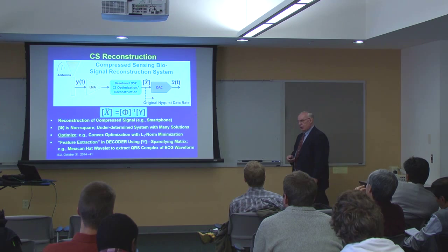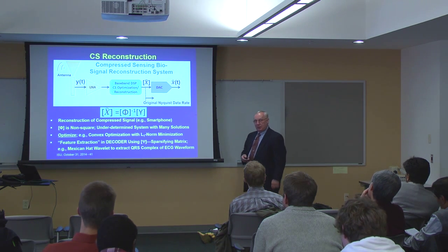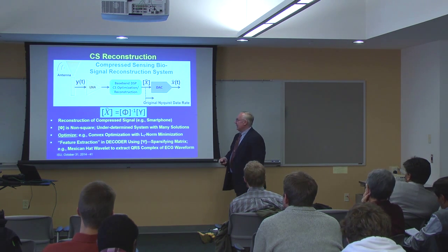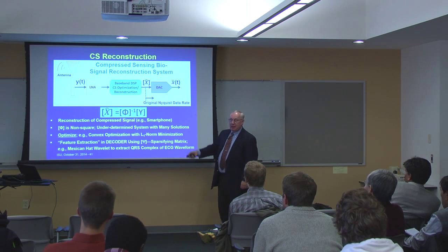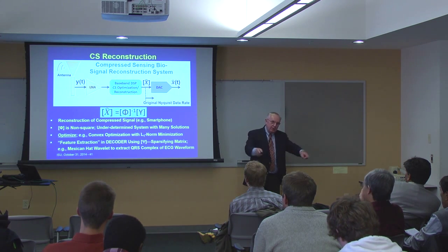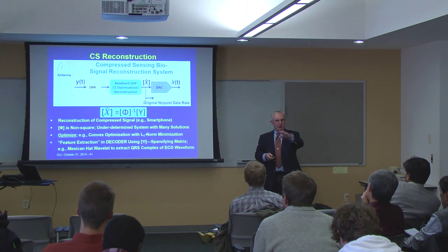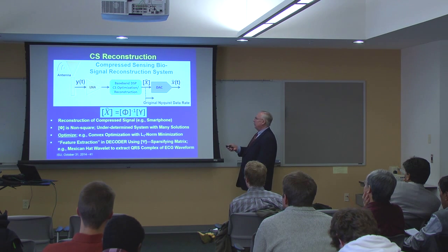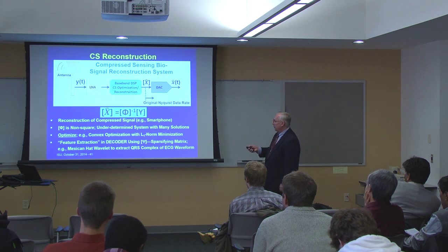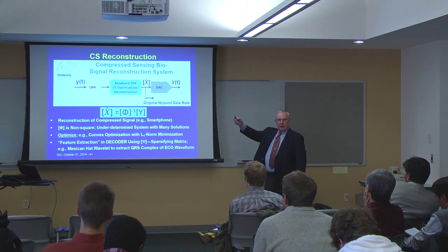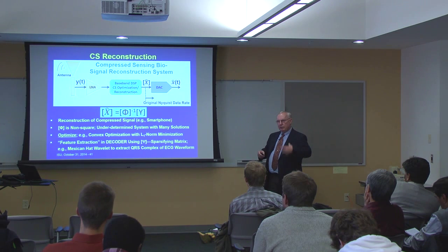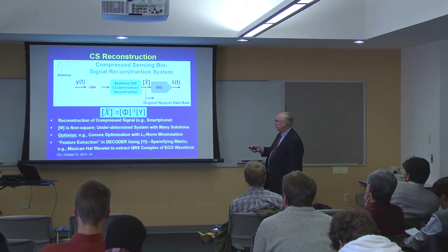And it turns out there is a wavelet called Mexican hat that you can use in the DSP box here to try to sort out that specific feature. So depending on what you're doing, you might choose different wavelets to look for different shapes and so on. But generally, that's a pretty complicated part of it. So if you do that in the doctor's office where there's plenty of power, you can plug into the wall and so forth, that's good. You put the rest of the stuff here, which is very efficient, that's good also.